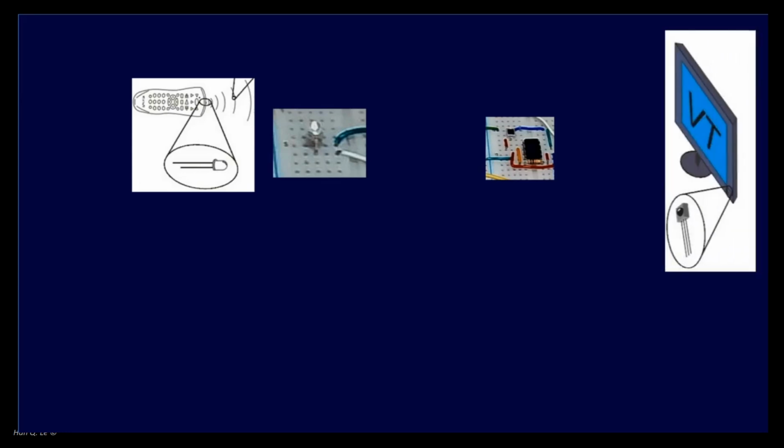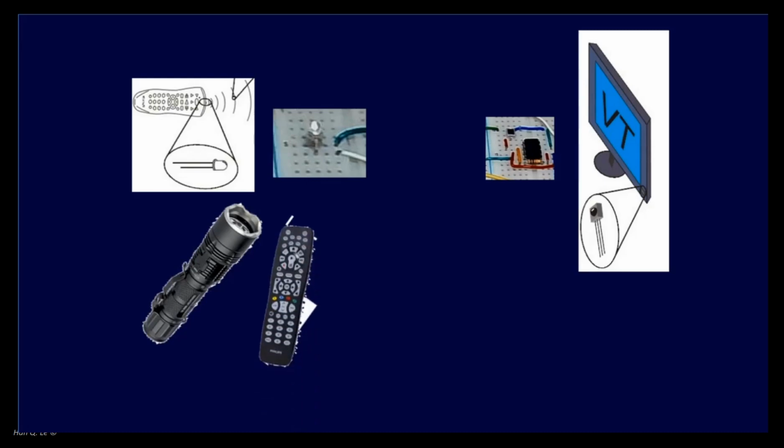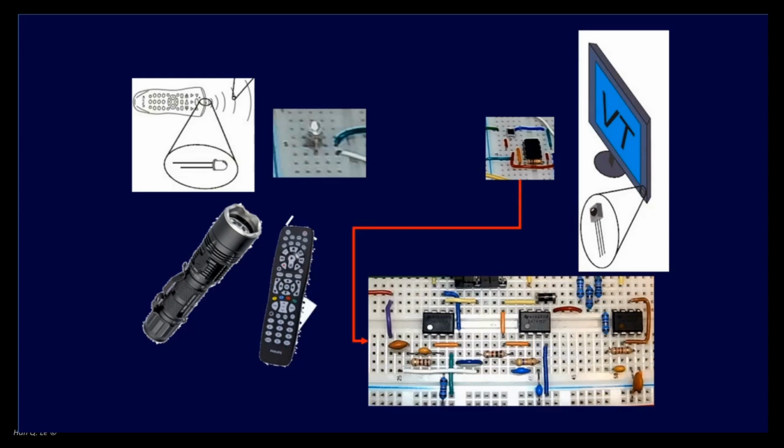An LED will act as the remote control, but with 9 kHz modulation, which matches the band-pass filter in Lab 6. The photoreceiver that was built in Lab 4 will assume the role of the IR receiver on the appliance. 2 sources of light will be the interferences: a flashlight that flashes at 250 Hz, which represents low-frequency interferences, and an actual remote control with a 38 kHz carrier to represent high-frequency interferences. The signal from the photoreceiver will be input into the circuit to test if it can tune in only the LED, and reject the interferences.